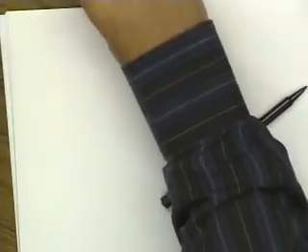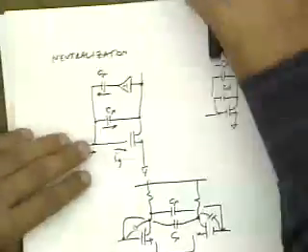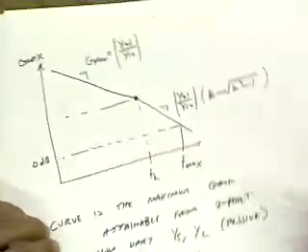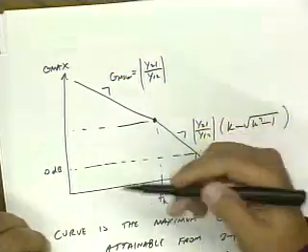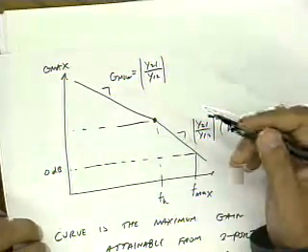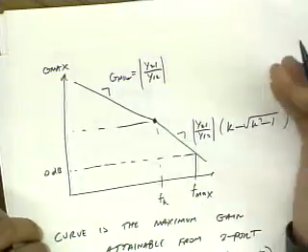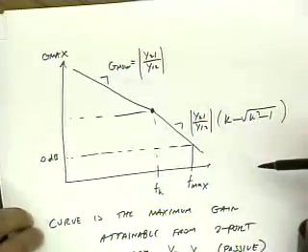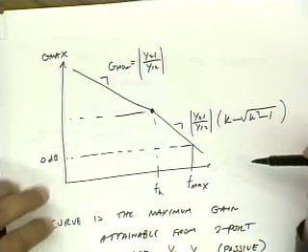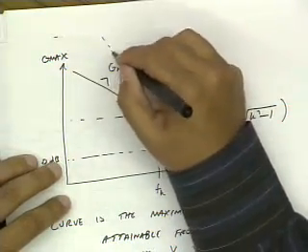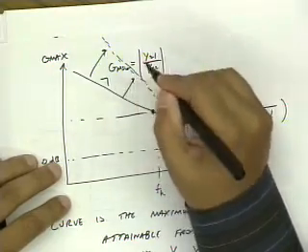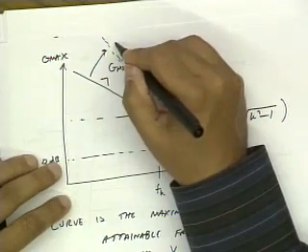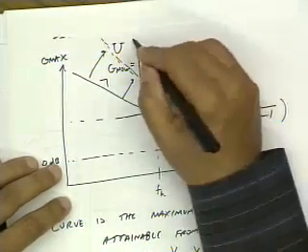Coming back to this curve, what you find is that in the case that your device is unstable, if you unilateralize it, then it becomes stable by definition, right? Because you're getting rid of the feedback. And then you can use this formula again for maximum gain of a unilateral amplifier, and you'll find that you can actually get more gain. So this is what we call the U, or the unilateral gain.